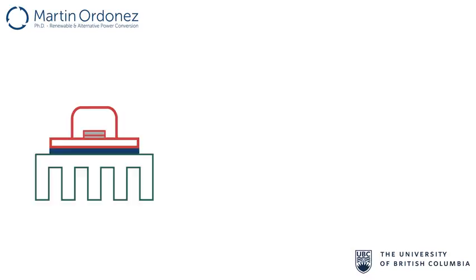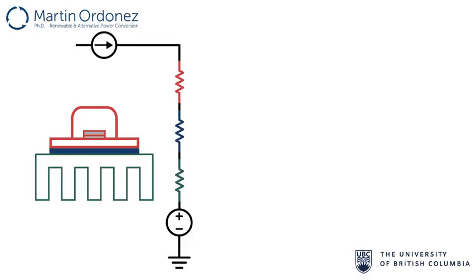Let's go back to our problem, the simple electrical circuit including a heat-sinked power MOSFET. We want to measure the temperature of the junction of the MOSFET and see how we can select the proper heatsink for the proposed power switch. Based on the analogy between the electrical and thermal phenomena, we can create an equivalent circuit that represents the physical device. Let's take a look in more detail at the problem.